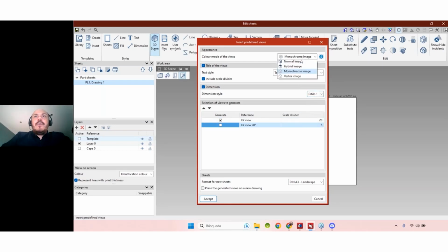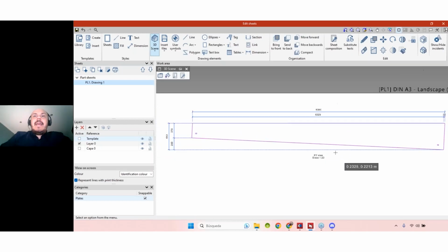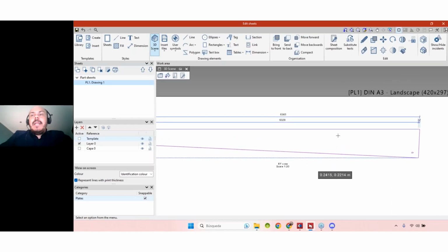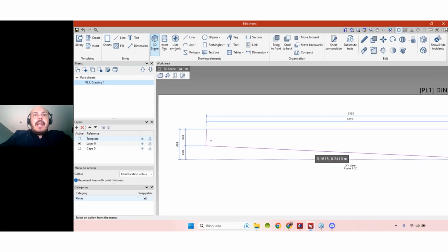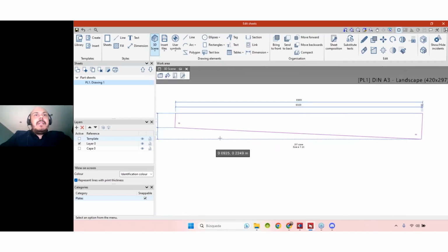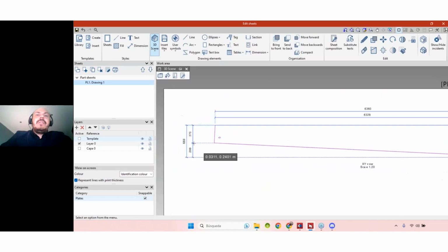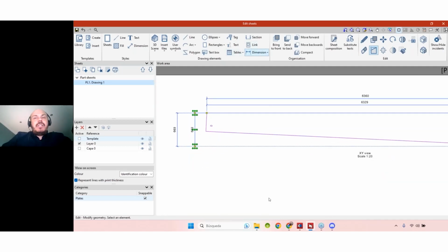We select this tile. Let's put on vector and maintain the dimension selected. And as you can see here, this bin in this case, or this part of the bin, it's already with the dimensions here. Okay, and again, it's the same situation. I have here some details, 32 millimeters there. Here we have these dimensions here. If we want, we can edit that guy and delete or modify the dimension, no problem. Or then add more dimensions if we want.